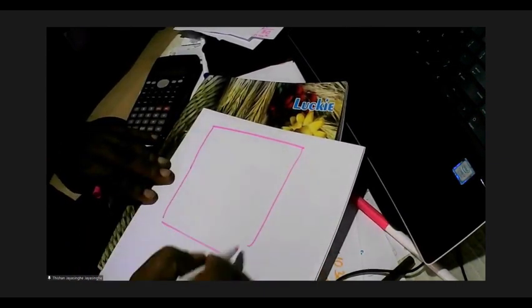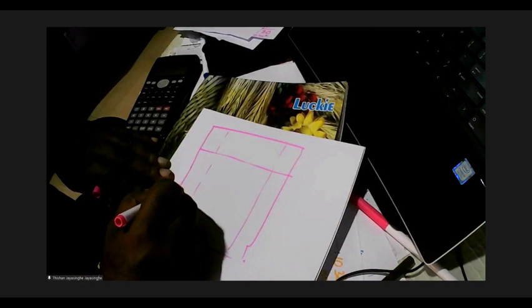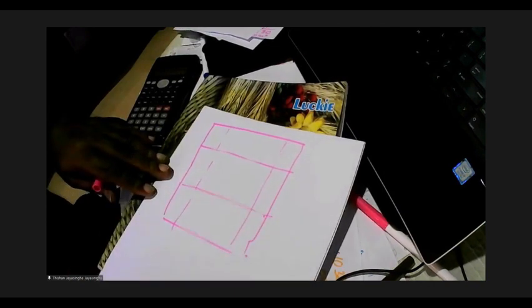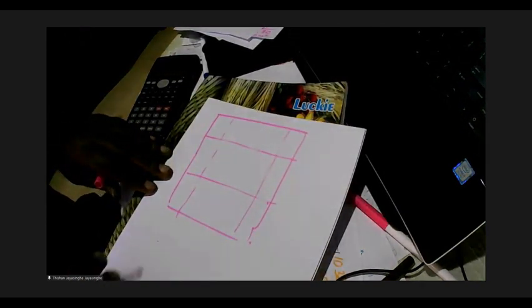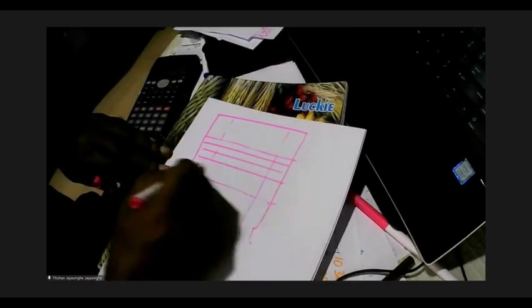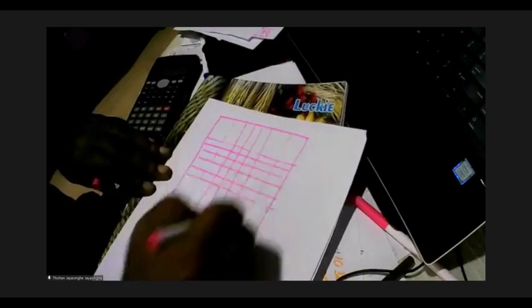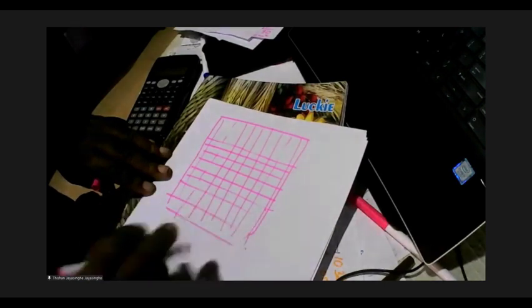now when you are doing the detailing, generally we know the middle strips will carry higher loads. So some people actually tend to have a lower space in this and then a higher space in this.